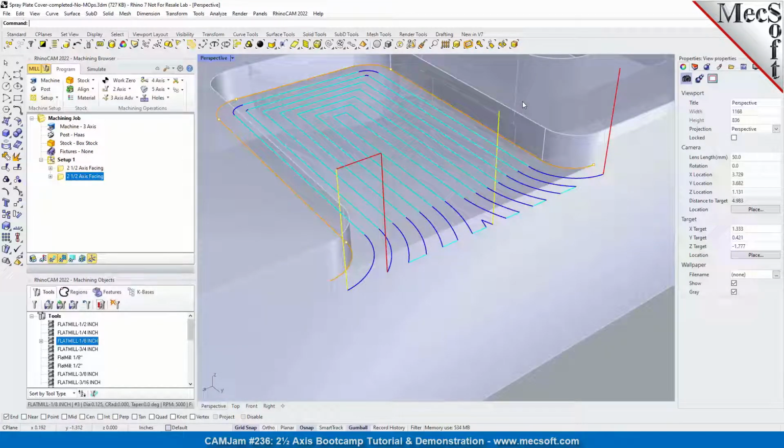And so Don, one quick note on the open facing. You picked it very quickly, and I just want to emphasize that. What this operation is doing internally, when it looks at this open curve in facing, is it's actually putting a line segment from the end point to the start point of the curve.